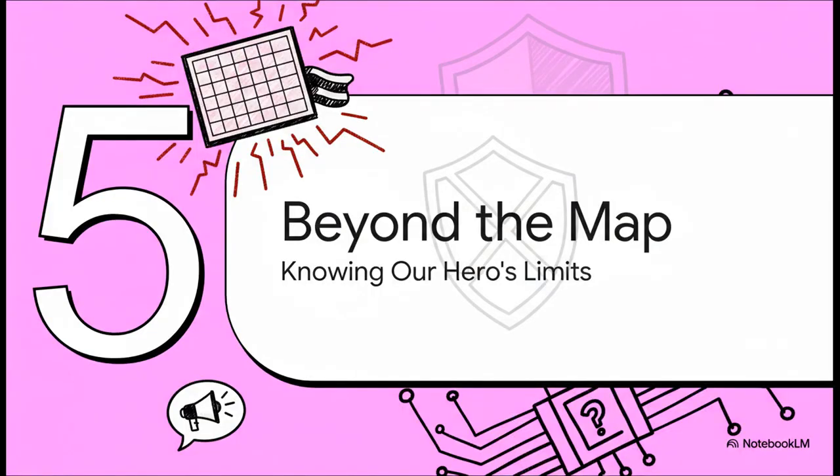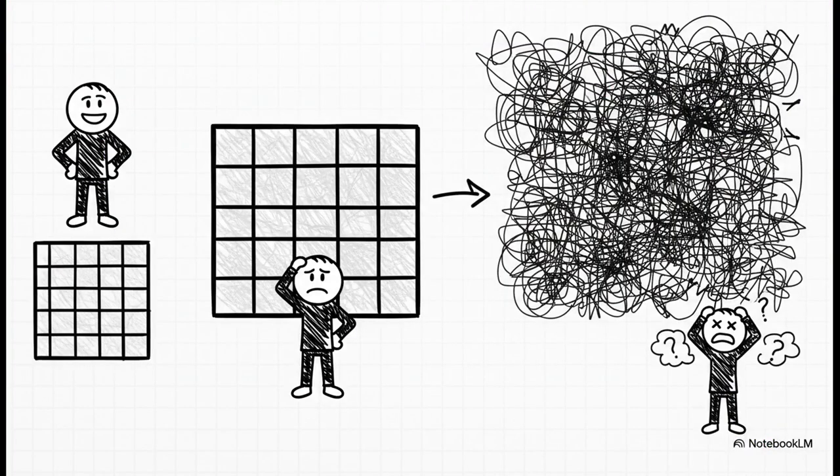Now, our hero, the K-map, is absolutely amazing, but it's not invincible. Like any hero, it has its limits, and it's really important to know when to call for some backup. You see, the thing is, K-maps are a manual tool, right? We humans have to draw and read them. And they work beautifully for problems with up to about 6 variables. But as soon as you go beyond that, the map just gets huge. It becomes way too big and visually complicated for us to handle on paper. It gets very, very messy, very fast.